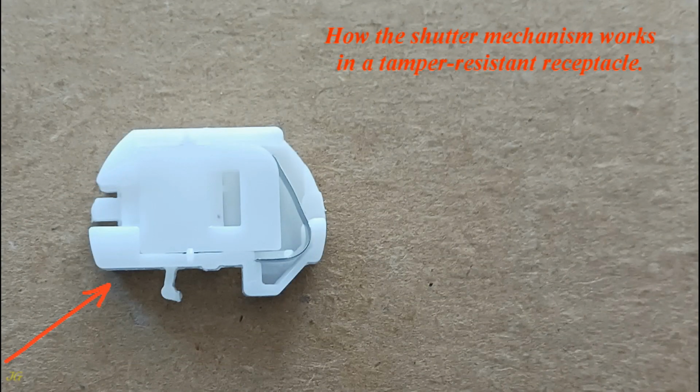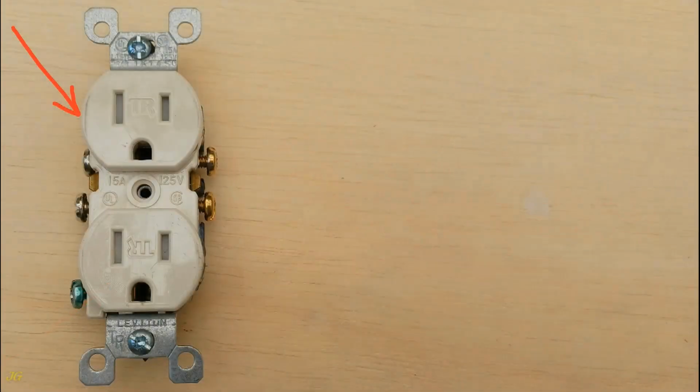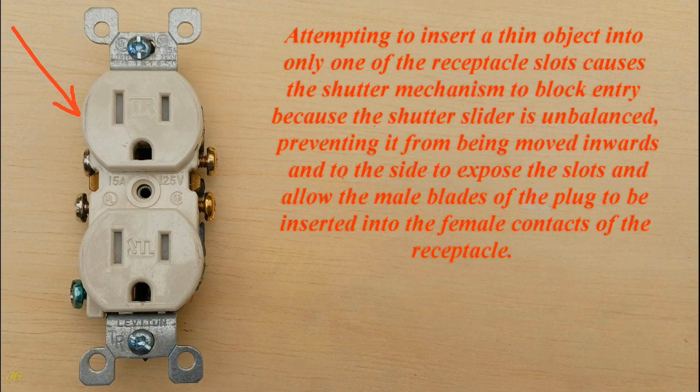How the shutter mechanism works in a tamper-resistant receptacle. Attempting to insert a thin object into only one of the receptacle slots causes the shutter mechanism to block entry because the shutter slider is unbalanced, preventing it from being moved inwards and to the side to expose the slots and allow the male blades of the plug to be inserted into the female contacts of the receptacle.